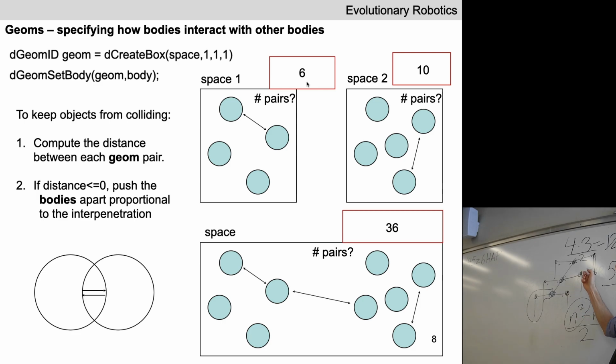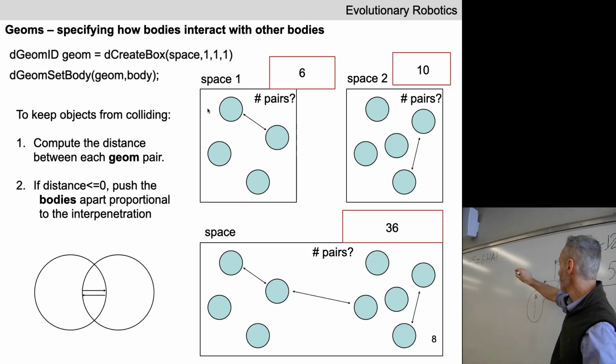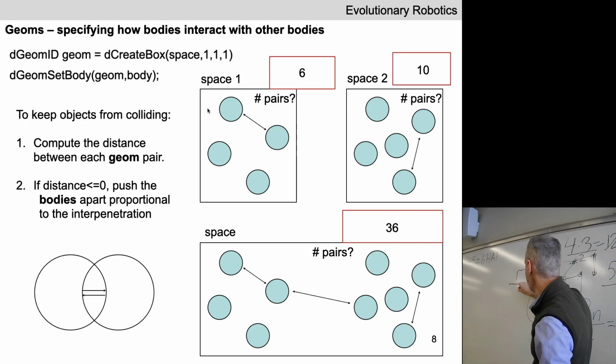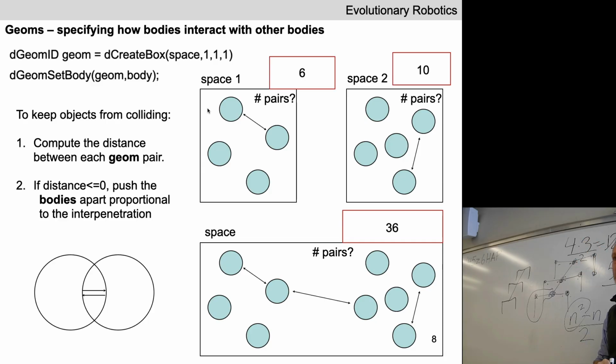You put all of the links of this robot in one collision space, and you put all of the links making up this second robot in a second collision space. At every point in time, among other things, your physics engine will detect whether the front right leg comes into contact with the front left leg, and it doesn't allow interpenetration. It says that shouldn't happen.